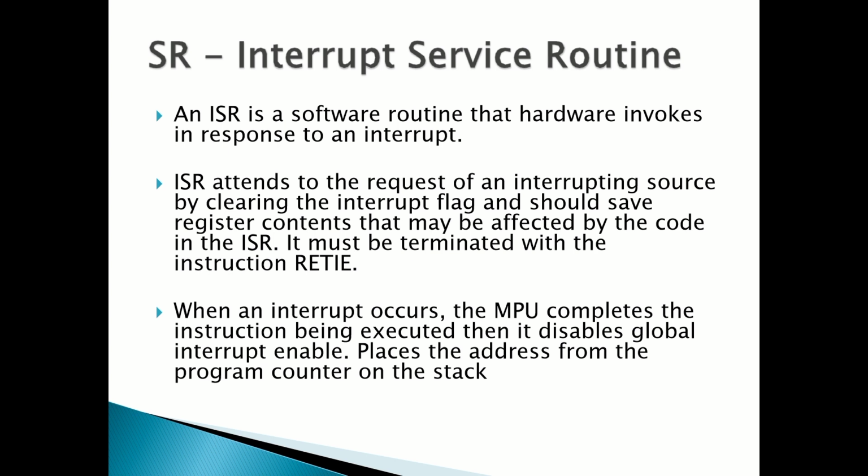When an interrupt occurs, the MPU completes the instruction being executed. Then it disables the global interrupt, enables the interrupt, and places the address from the program counter on the stack.